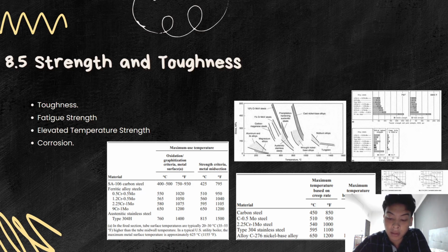First, as-rolled carbon manganese steels. Second, as-rolled high strength low alloy or HSLA steels, which are also known as microalloy steels. Three, heat treated normalized or quenched and tempered carbon steels. And last, heat treated low alloy steels.